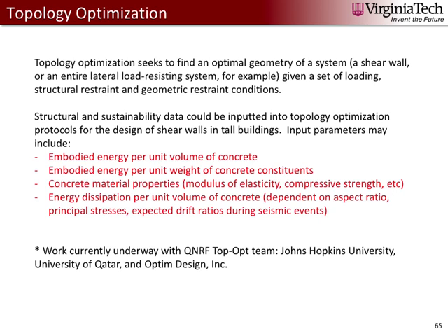embodied energy per unit weight of concrete constituents if we wish to make the mix designs customizable, material properties of the concrete including modulus of elasticity, so we can determine the stiffness and if that's okay for our solution, compressive strength, and so on. And lastly, energy dissipation per unit volume of concrete, which of course depends on the aspect ratio of the wall, principal stresses, expected drift ratios during seismic events, and so on. And this work is currently underway with the QNRF partners to Virginia Tech, which include Johns Hopkins University, the University of Qatar, and Optimum Design Incorporated.